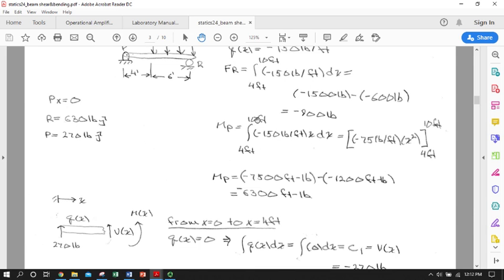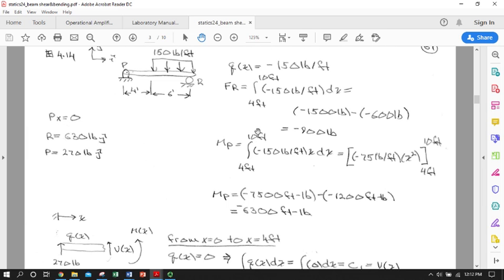We'll go through the same exercise to find its resultant moment, integrating that negative 150 pounds per foot times x between 4 feet and 10 feet, and the limits of integration really matter here. We're going to start slapping a coordinate system on at the very beginning of the beam, so it's not relative now. We need to be careful to reference everything back to what we've decided x equals 0 is. So x equals 0 is over at point P. So we're going to integrate negative 150 pounds per foot times x with respect to x between 4 feet and 10 feet.